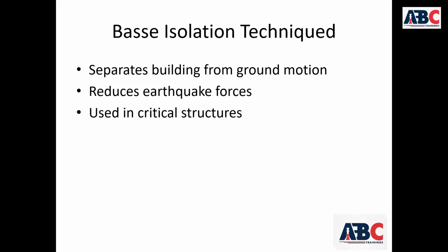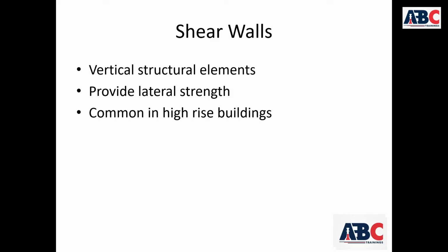Next slide is about shear walls. Shear walls are the most important structural element used in earthquake resistant buildings. Shear walls play a major role in resisting lateral forces caused by earthquakes and winds. What is a shear wall? A shear wall is a vertical reinforced concrete wall designed specially to resist lateral loads.